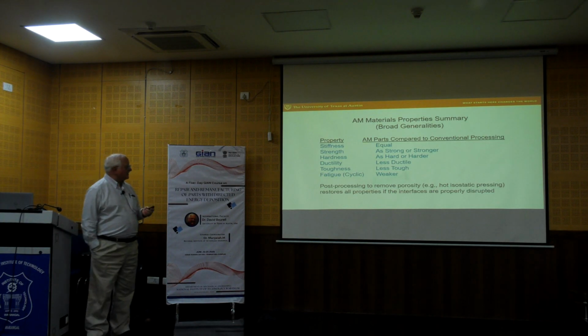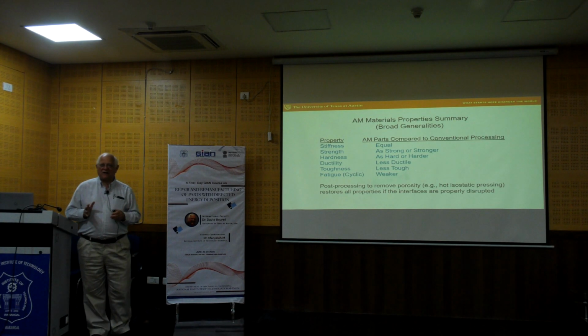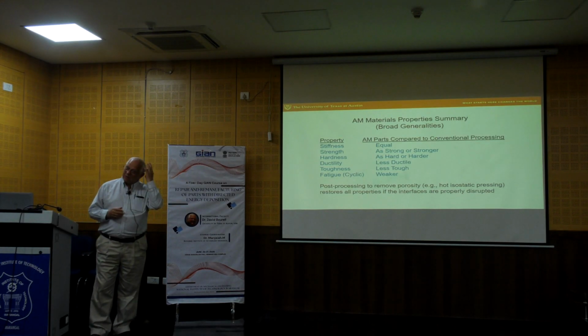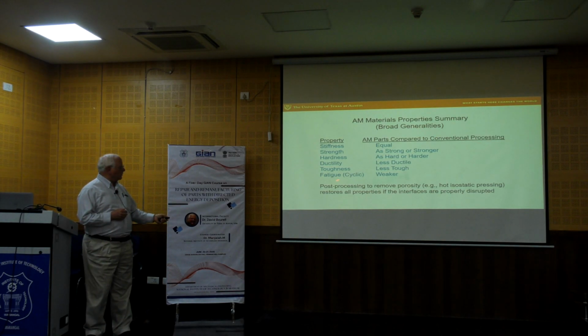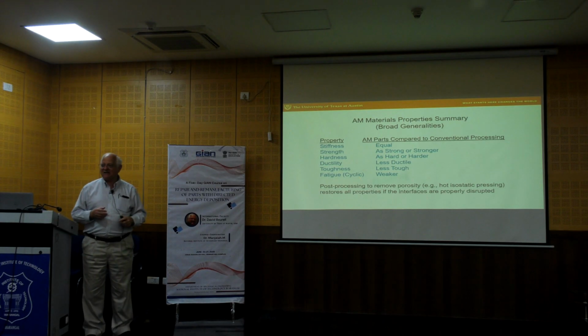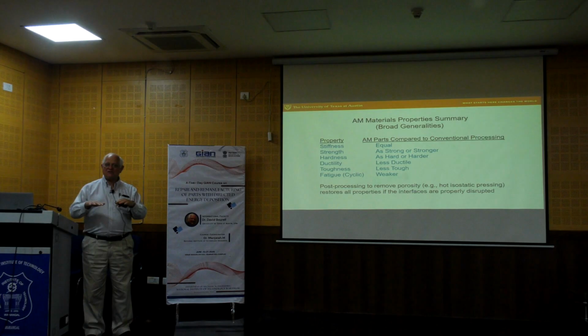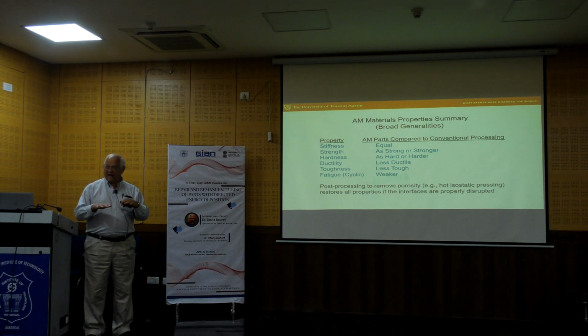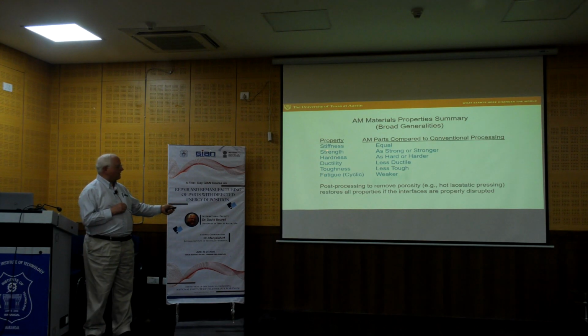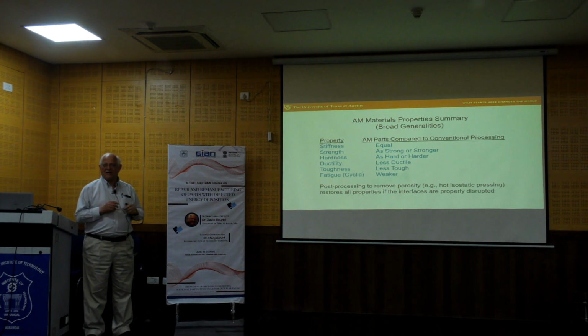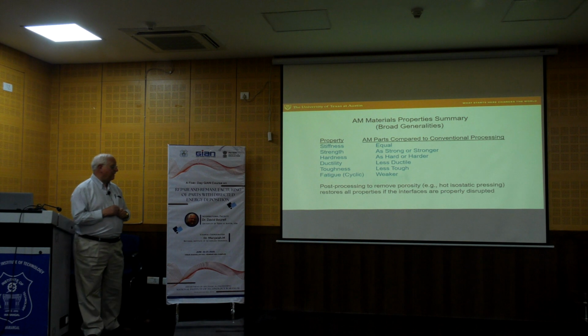So what we find is, if you really want to declare victory in terms of mechanical properties for additive, you really should be down here doing toughness and fatigue tests, because if you can get these parameters to match the forging or the casting, then you've really accomplished something. It's not very impressive to hit strength.